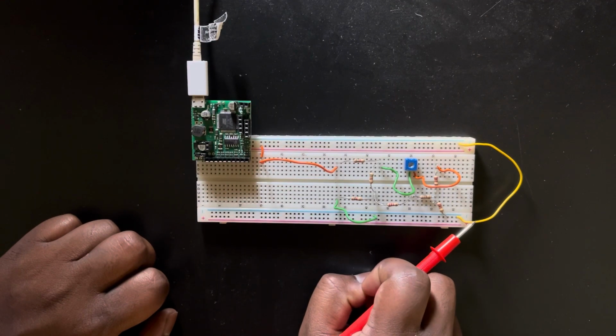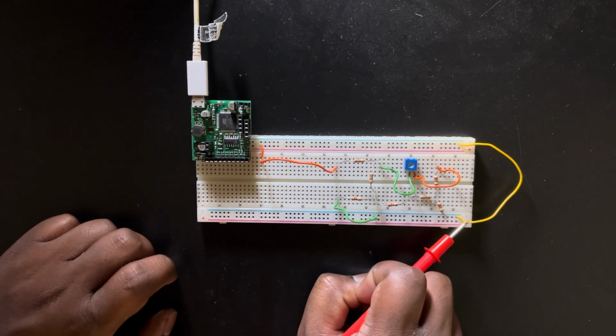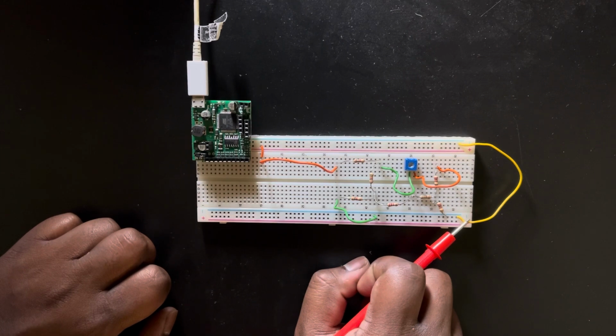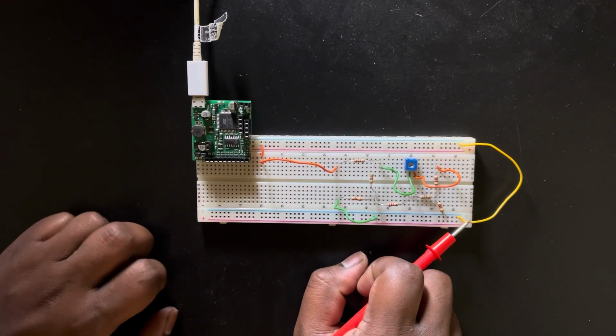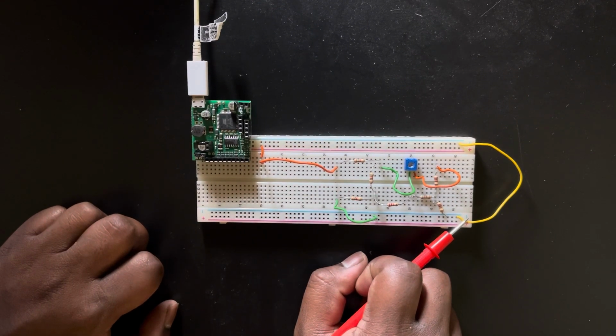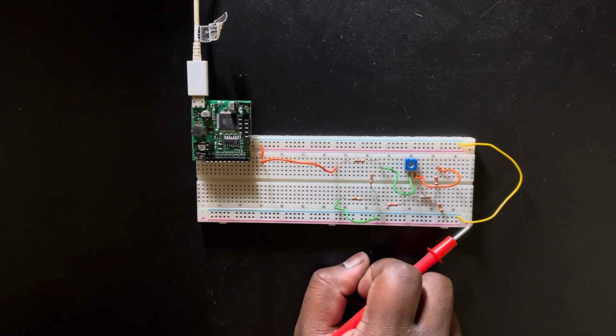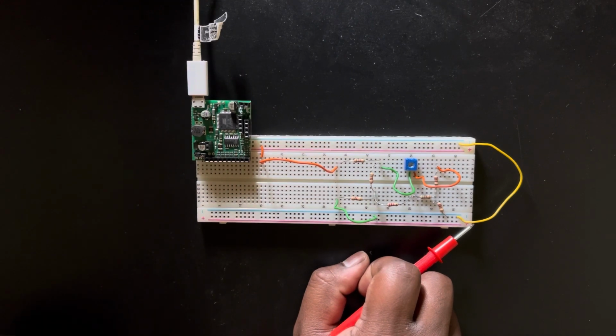Similarly, you can see node 6 and node 4, the resistor between those two nodes is 2.7 kilo ohms, right? I don't have 2.7 kilo ohms, I have 2 kilo ohms and 500 ohms. If I try to measure the 500 ohms, that one actually comes to 670 ohms. So I have 670 ohms in series with 2.2 kilo ohms, and that comes to around 2.78 kilo ohms.